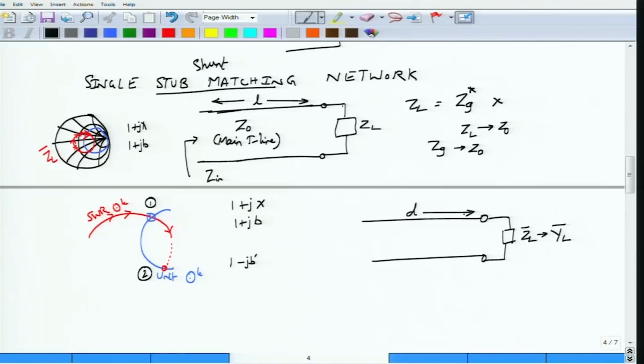And then you have moved a certain length L on the transmission line, so as to make the admittance out here, some YL prime, let us call this one, looking into the transmission line terminals of characteristic admittance Y0, equal to 1 plus jB, where B is the normalized imaginary part of the admittance. But it is at least one step closer to matching. Why? Because you only now have to take out this jB.